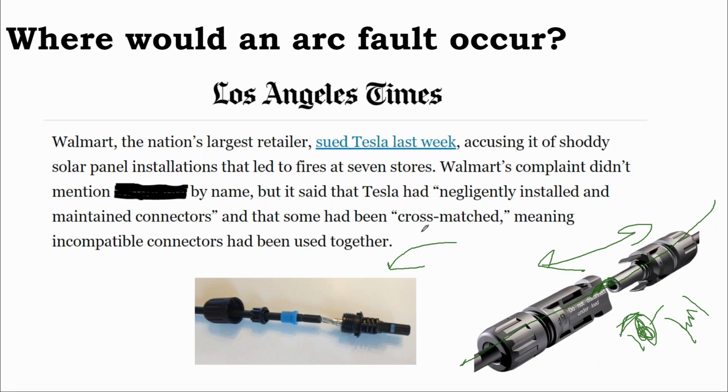And arc faults don't need to occur just in an air gap. Any loose wire terminations where the nut or the bolt is not torqued to the manufacturer's spec can cause arc faults. Stranded wiring that is poorly secured onto a terminal can cause arc faults. And back in the day, inverters did not have arc fault detection in them. And so perhaps the reputation of string inverters for being bulletproof was, to some regard, hiding some workmanship issues of installers, because an arc fault can be occurring with the equipment still operating.